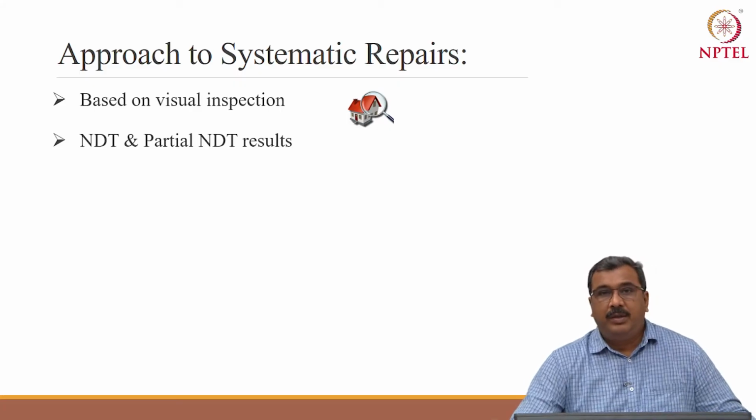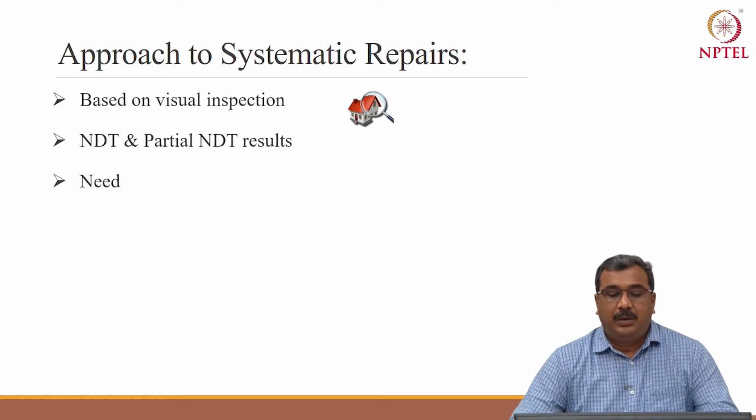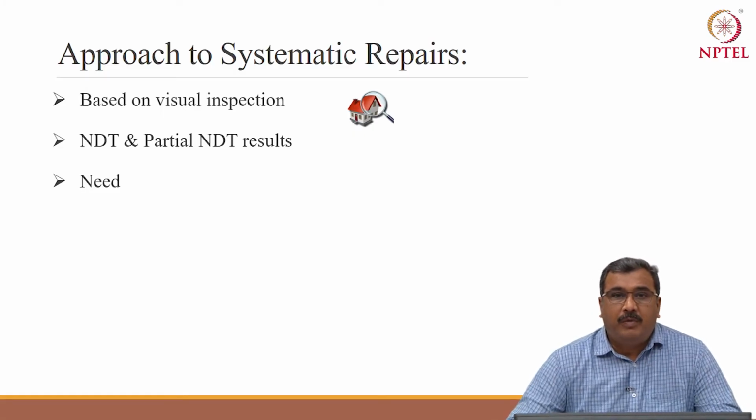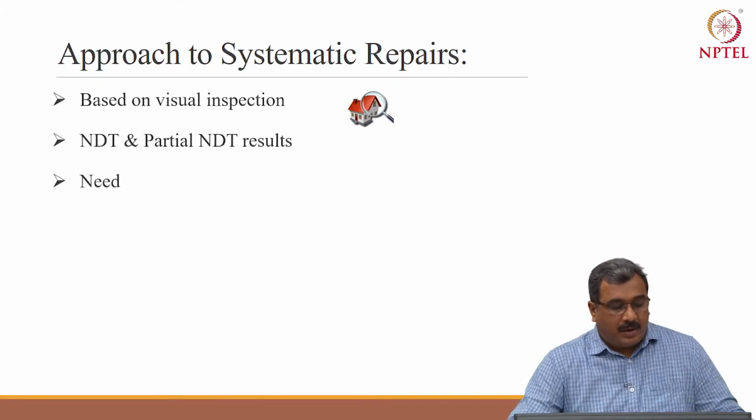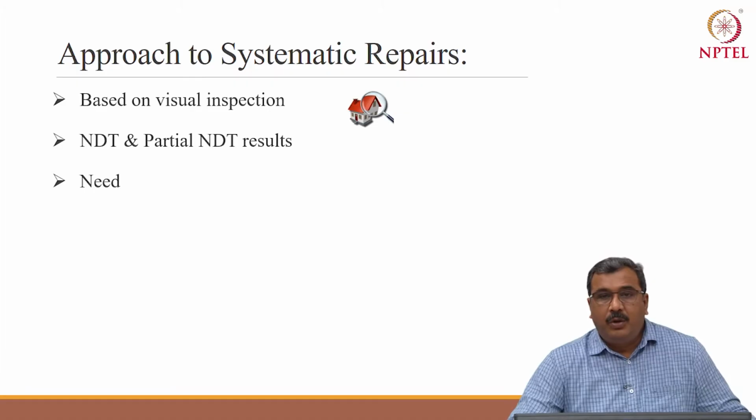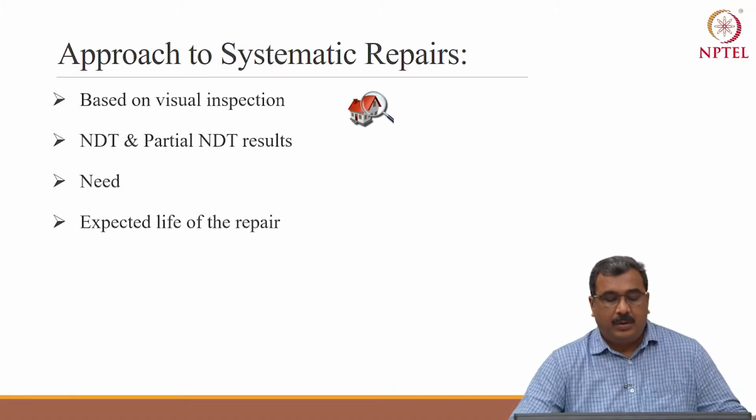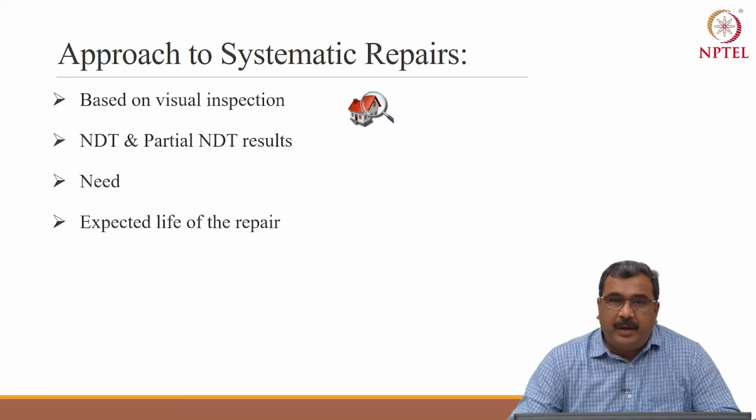Once you had done the visual inspection and carried out test, one should know why you need repairs and rehabilitation or strengthening of the structure. What is the requirement? You can ask to the owner or a user, and expected life of repair.